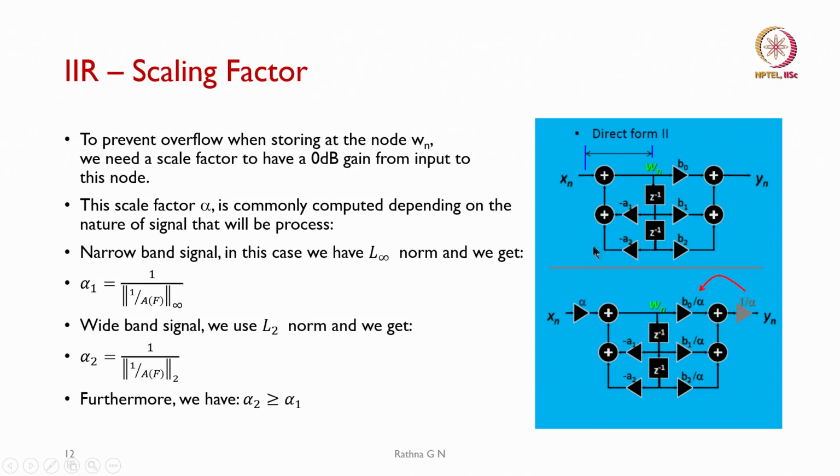So, because it is the same sign, the magnitudes are going to be added. So, I may have an overflow or an underflow. To avoid this overflow and underflow, we have to have a scaling factor. You may wonder why we chose a scaling thing: that is the barrel shifter, which does either shift right or shift left, required for scaling my input in this case.